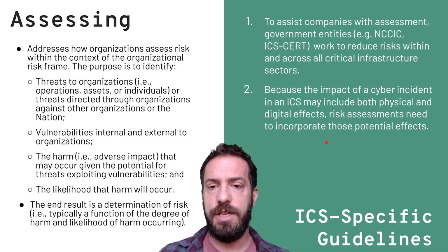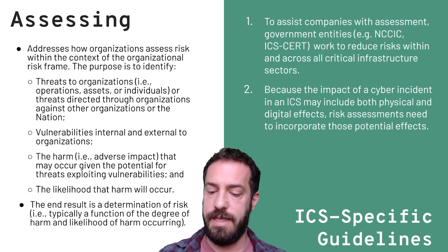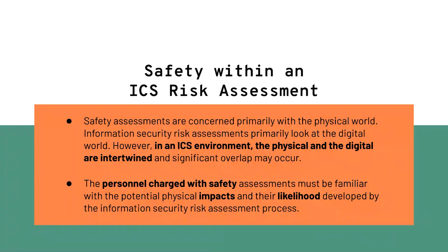But during risk assessment, because the ICS include both physical and digital effects, we need to incorporate those into our risk assessment. So in more detail, first is safety. A safety assessment will be concerned primarily with the physical world, while information risk assessment is looking at the digital world. In an ICS, however, those two are intertwined. If something goes wrong in the digital world, this can affect the safety as well. So whenever we do risk assessment for ICS, we have to make sure that the personnel charged with safety assessments are also part of the information security risk assessment.